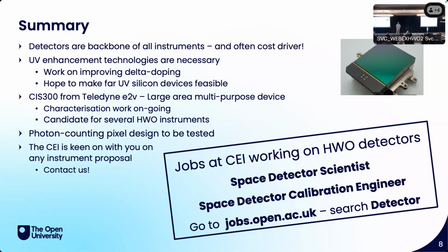I also happen to work with CMOS single photon counting detectors. They're from BAE, but you're not going to like this question. It's about quantum yield. We're also trying to measure it, and we're having some trouble. We're using the photon transfer conversion gain method, but I'll just say we're getting some weird results. So do you have any plans going forward, or are you going to use the same method? I'm curious about your idea of how to quantify quantum yield.